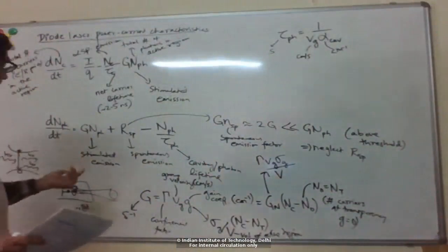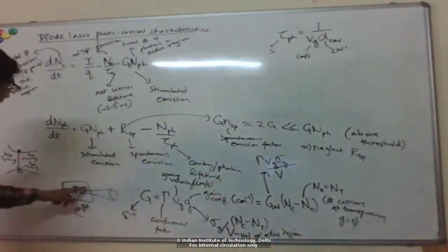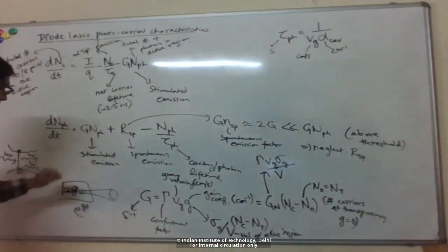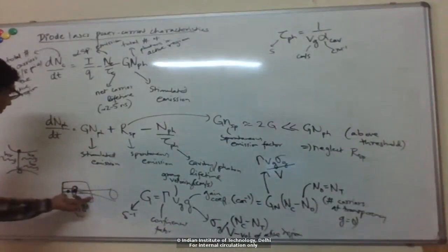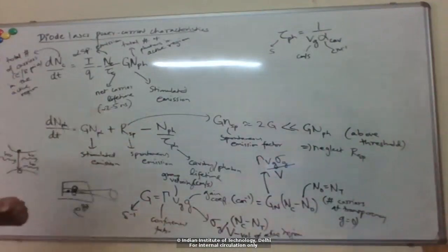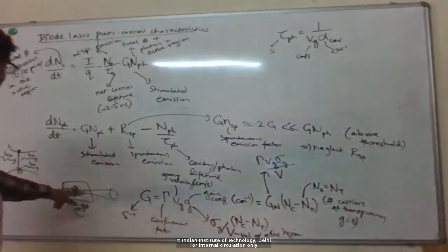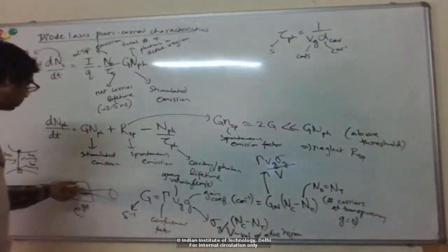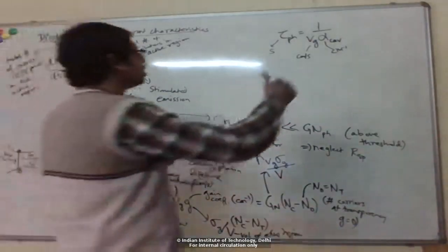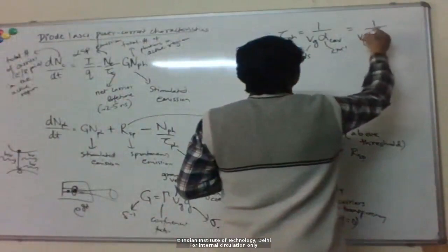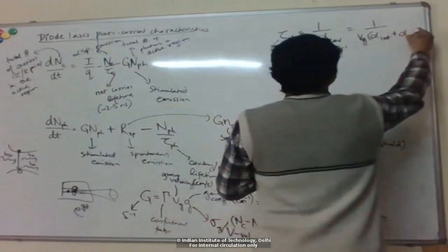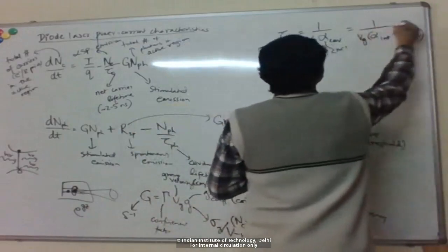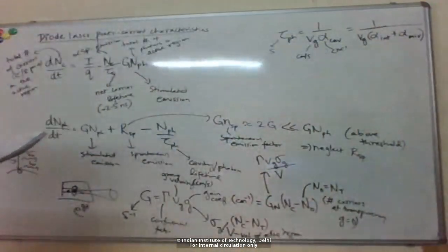And we saw that the loss has two contributions, right? One is some internal loss, which could be some absorption in defects or some scattering due to roughness or something, so there is an internal loss coefficient. And then, of course, from the mirrors at the edge of my device: these mirrors are not 100% reflecting, so the photons are actually coming out, so there's a loss there. So one is the internal loss coefficient, and the other is the mirror loss, which gives me my total cavity loss.